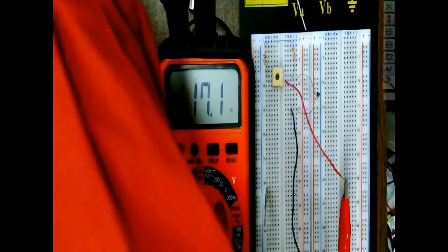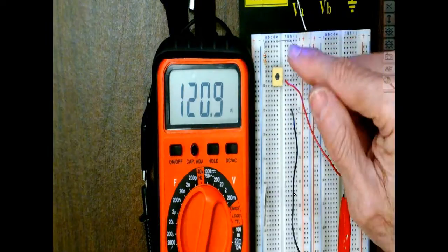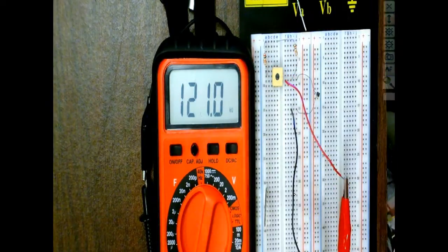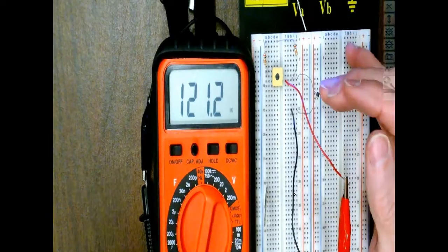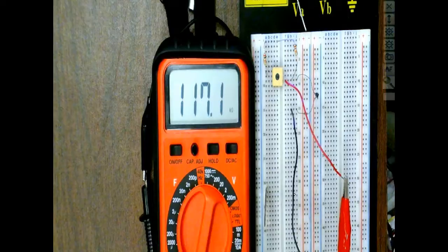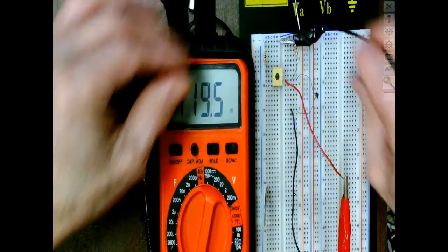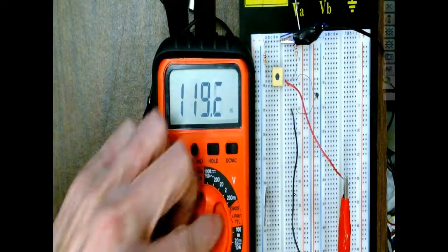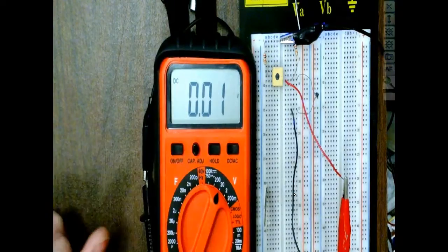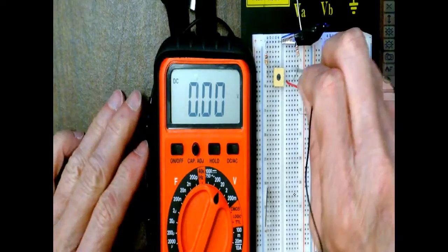But the problem is, I can't see what's going on as far as getting a voltage out of this. So what I have here is a 20 k ohm resistor. You can see this guy right here is pretty high, but we should still be able to see that. And I'm going to use a 5 volt source. I'm going to put my meter on DC volts, and move a common across my resistor.